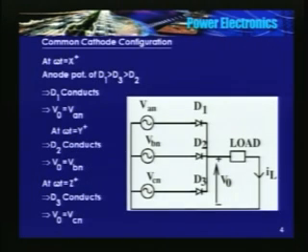So here is the bridge. First we will do the uncontrolled case. The 3 diodes D1, D2, D3 form a common cathode configuration, and the load is connected between the common cathode and the star point. Therefore, the diode whose anode potential is highest will start conducting.